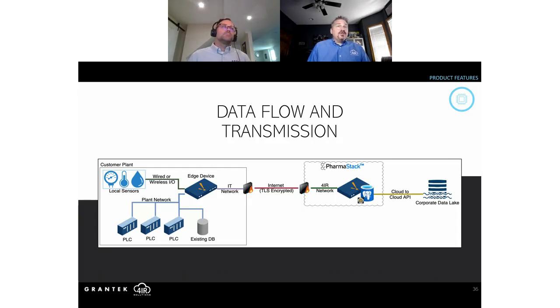During normal operation, this flow is consistent and the data arrives and is stored in our time series optimized cloud database in real time, close to real time. If there's some issue with the internet connection, which we know happens from time to time, the edge device will store the information that's being collected, including the arrival timestamps, and wait for that internet connection to resume. The system is capable of handling up to 1 week of information in its data queue. Once the connection is revived, the edge device will forward all of the missing data to the database, including the correct timestamps that were marked on arrival.